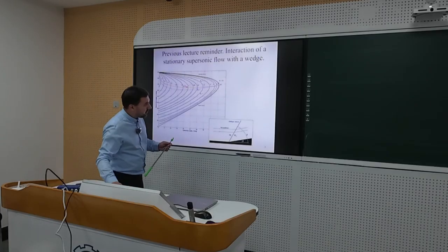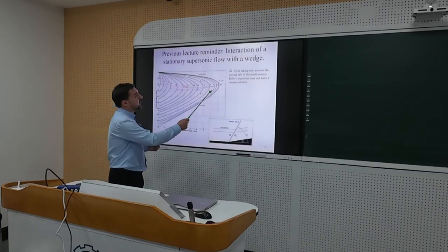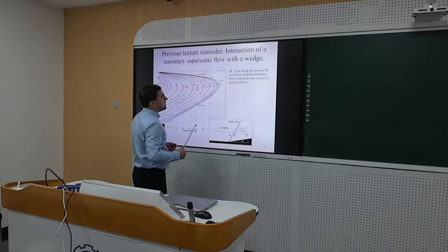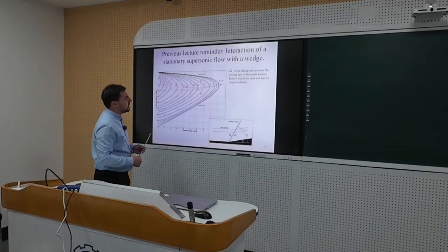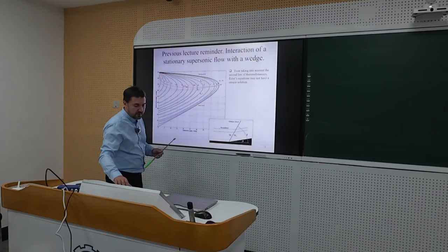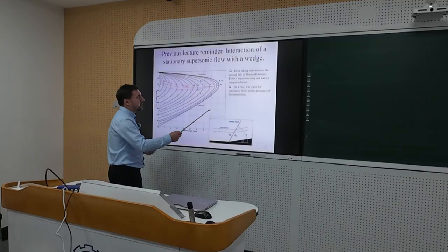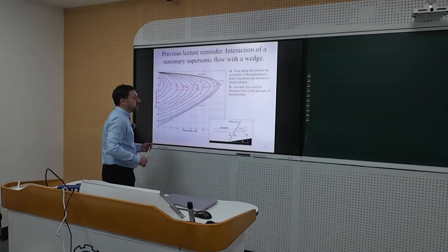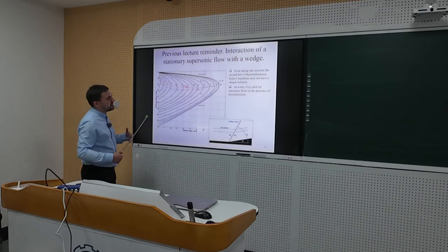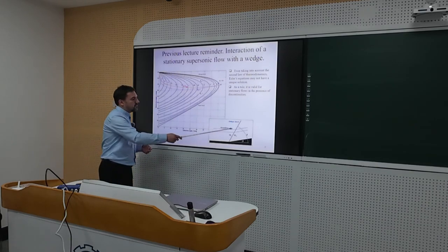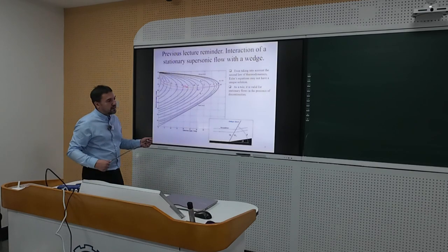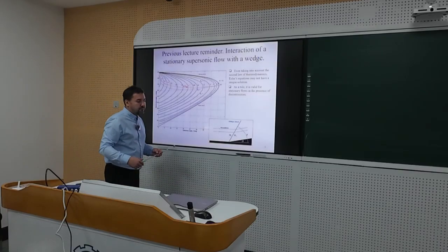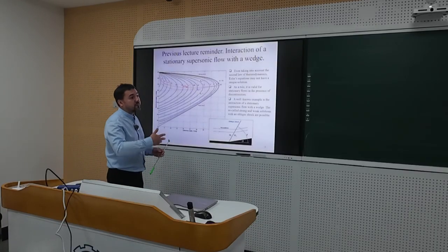So the most important thing here is that even taking into account the second law of thermodynamics, Euler's equations may not have a unique solution. So this is the first point. The second point, as a rule, is valid for stationary flows in the presence of discontinuities. So usually this happens when you have solutions in the form of discontinuities, shock waves. And that is typical for compressible media.